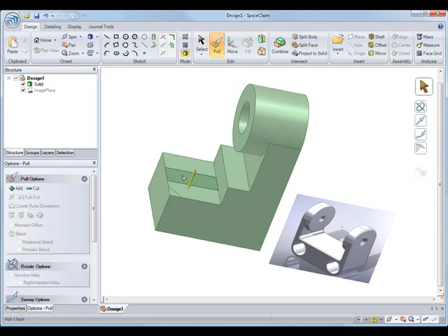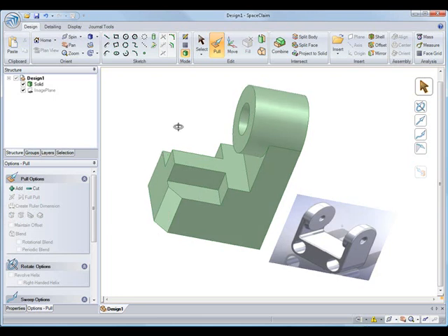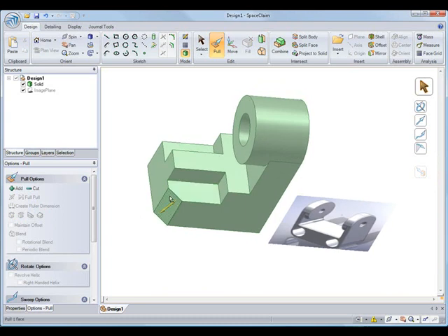So now we'll just pull up this material to add the rib going through it, and pull it up to our other stepped area, and I'll actually just cut out this region here. So I've only cut it out on one side because I want our part to be symmetric. So I'm actually going to mirror over a couple times.